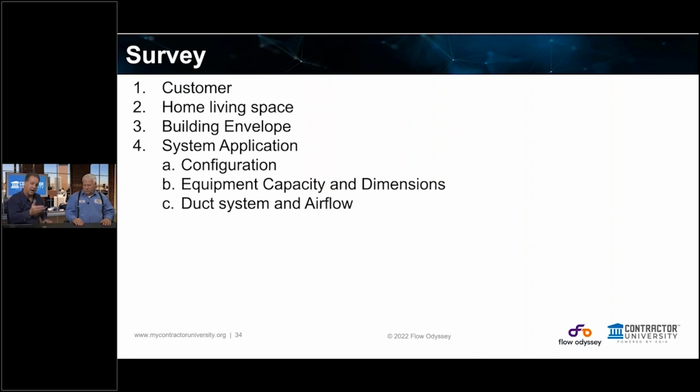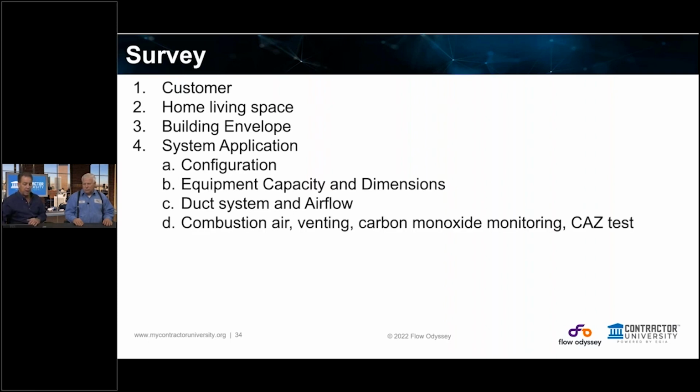dirty ducts, looking inside, and taking pictures. Pop off the return grill and take some pictures inside there. Use a borescope or an endoscope to take pictures inside the ductwork. Again, like Eric said, make this visual to the customer. Because if it's just you talking about it, that's opinion. But having the pictures, having some drawings, having some notes, taking some tests is really going to help you. Take pictures, lots of pictures.